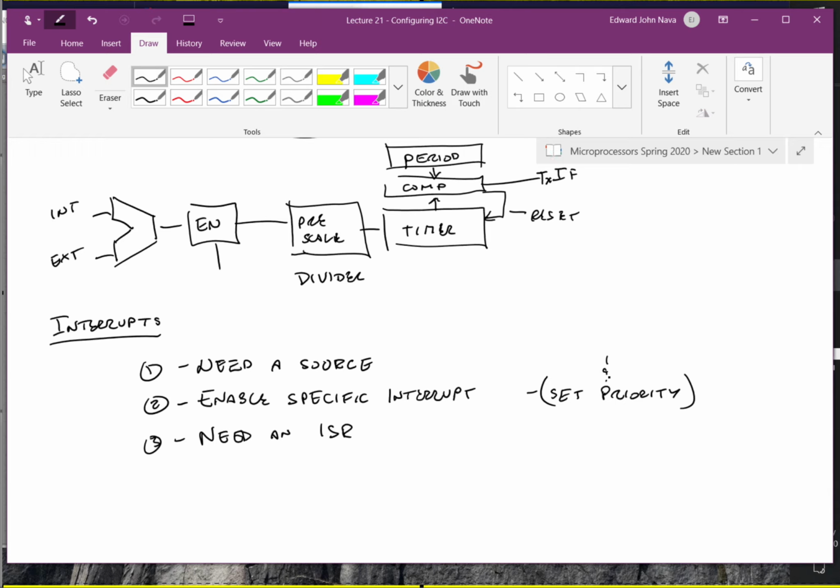And if I have my highest priority interrupt, then there's going to be a shadow register set that we can use for the level 7 priority. Or there's an internal stack that we can use, and so when I'm doing interrupts, there's a little bit of overhead in that process. And we also have the ability of interrupts to interrupt other interrupts by using the appropriate level of priorities. Okay, so we have 7 levels, and then we have 4 sub-levels for a total of 28 possible levels. Okay, so then we talked about interrupt service routines.